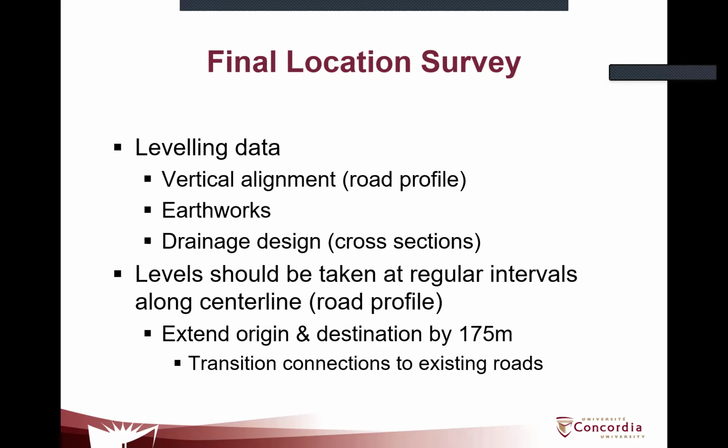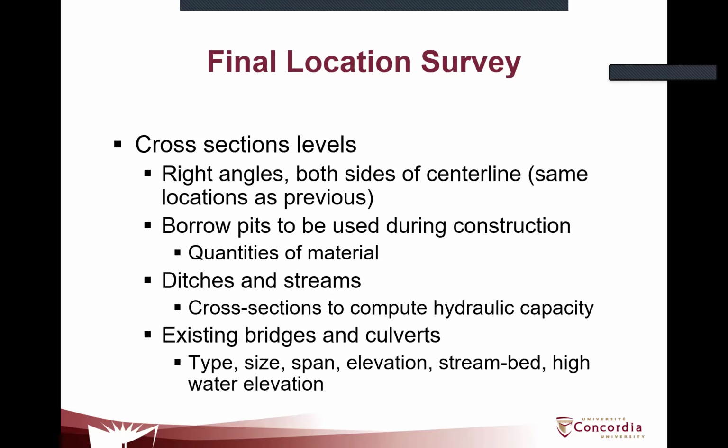So the levels should be taken at regular intervals. It depends on whether you have curves or not. If you don't have curves, you can take them every 100 meters. But if you have curves, then you have to take the levels more often to create the road profile. And so with this, you will have the cross sections, and you will need the different elevations and levels of the cross sections. So the center line and then at different points across the cross section of the road.